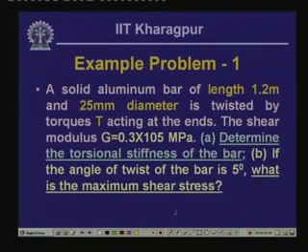Now, if we look into the evaluation of the stress and the deformation because of this non-uniform distribution, either in the material diameter-wise or in the change in the twisting values: when you compute the stresses for different segments, whichever gives the maximum value will be the governing stress. And rotation-wise, between the 2 ends we will sum them up, and the final rotation will be the rotation governing in the shaft. These are the 2 aspects which are a little different from when the bar is uniform and subjected to uniform twisting moment. Well, with this background, let us look into some examples wherein we apply these theories.